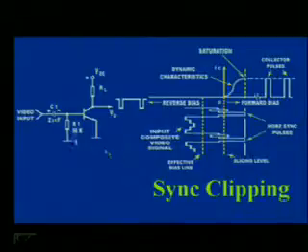with the result that the base of this transistor is forward biased with the help of sync pulses and goes into conduction, and syncs are separated.